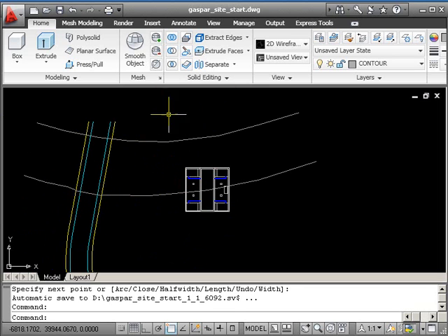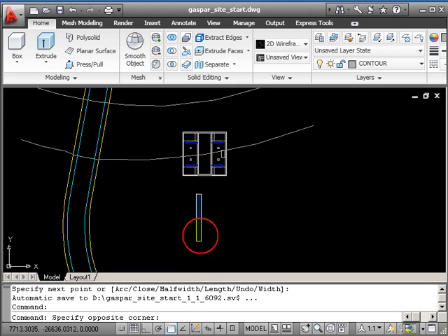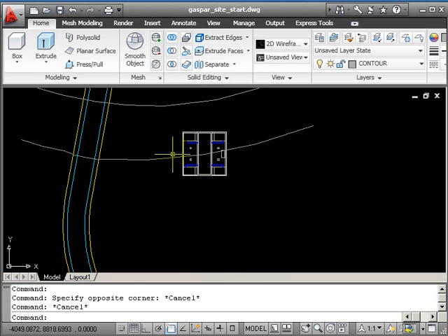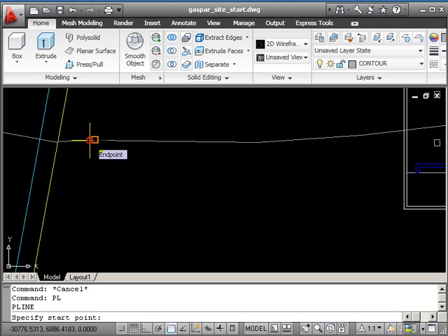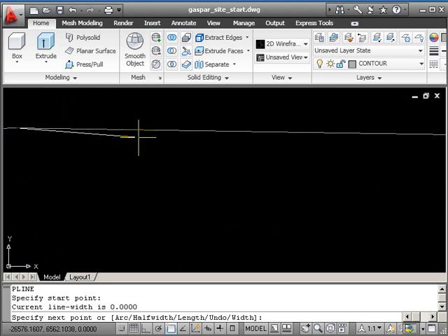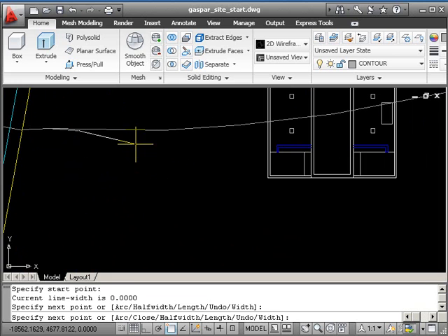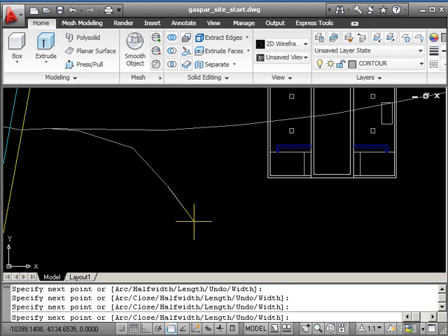Now let's say the high point is up here and the ground slopes down in this direction, sloping from high to low. Now to make our house buildable, what we need to do is change the contours. We need to belly out a wee bit here, so there's a bit more flat land. So if the distance between these two contours was widened, you've got more level land to build on. So let's say we come away from this one a bit sooner. So this is like the proposed shape of the land.